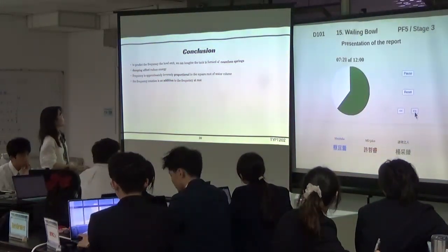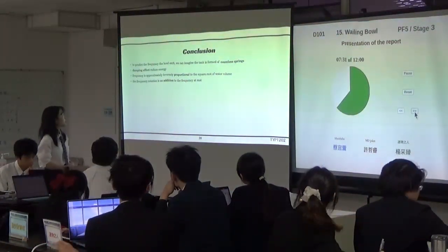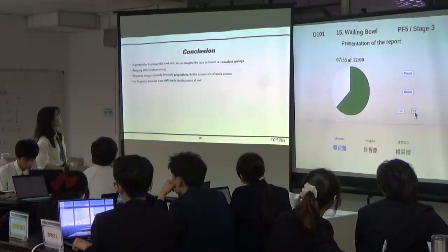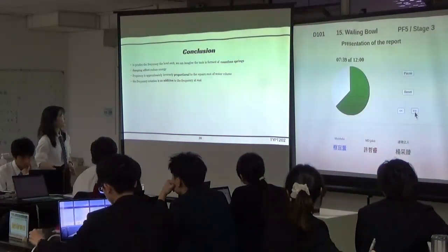And the damping effect only reduces the energy and will not change the frequency. And the frequency is approximately inversely proportional to the square root of the water volume. And the frequency when rotating is in addition to the frequency at rest.